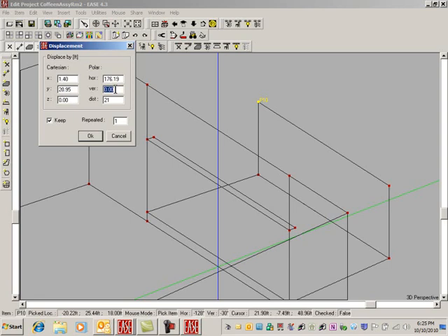What if I did it wrong? I'll make it clockwise like this, and it's going to turn out to be yellow, and I know I want it white because I'm looking at the outside of it. And say okay, there it is, yellow. Right up here is an icon that says invert selected face. Yes. Now it's right.